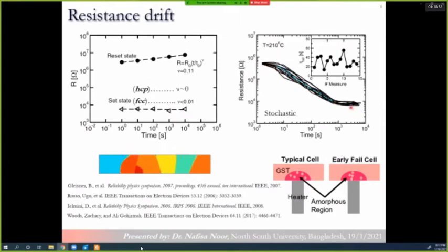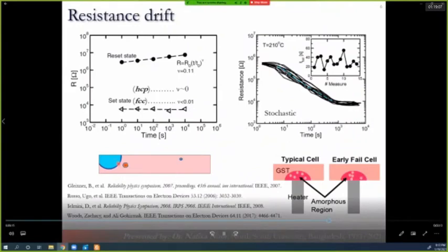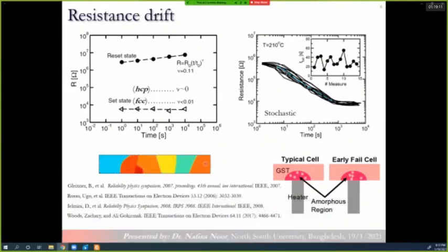The reason behind that is when we have crystallization in the amorphous region, some crystalline islands nucleate, and after these nucleations, the nucleated crystalline islands grow in size. For example, here you see that one island is growing, and as other islands pop up, they are all growing together and merging together. This nucleation of different islands can be at different locations and at different times, even when we cycle the same cell during the crystallization of different cycles. Because of these variations in their locations and the timing of their popping up, we can have different decreases of resistance over time, and that is why we have different trajectories for the spontaneous data loss trend in the PCM.